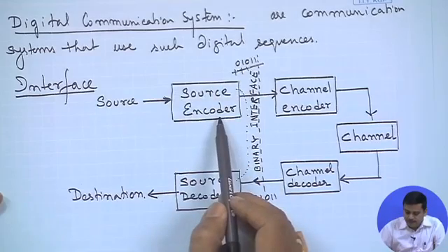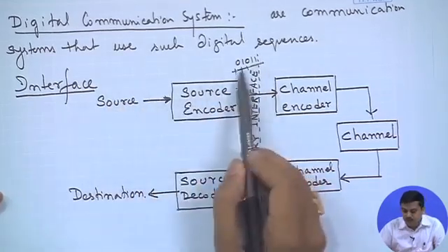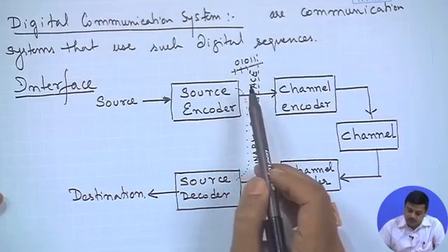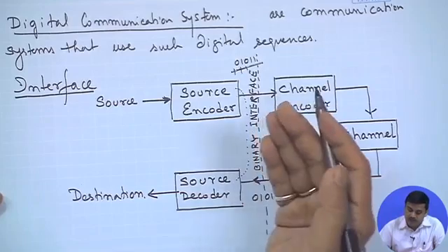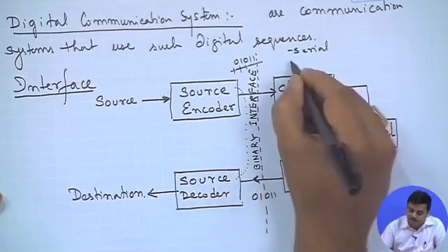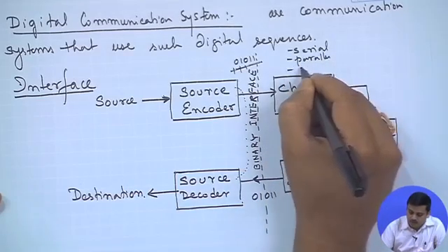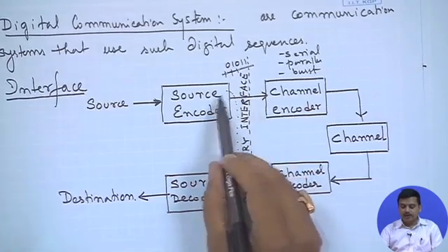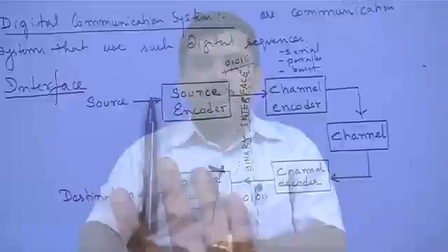So, when the source coder is being designed or implemented, it takes a source and produces a sequence of zeros and ones. That is it, because it knows the next one is going to take the sequence of zeros and ones. When it connects to a particular channel encoder, specific characteristics means specific realizations. It could be that there is a serial input, it could be parallel, it could be burst. Depending upon such specific interfaces, it makes outputs available in such a manner. If it is burst, then there would be some words and some controller pin which would be activated and it would send a few bits.